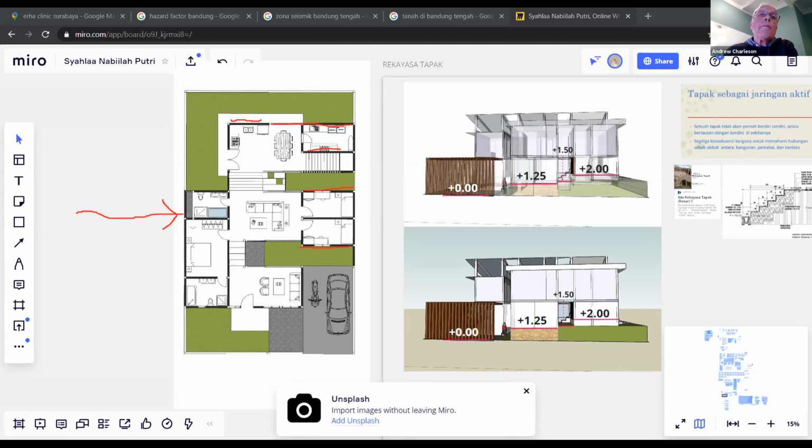My plan is still not quite fixed. Yeah. Okay, well, I think you need some strength at the front here. You need a good bracing wall of confined masonry with a small window there. That would be okay.